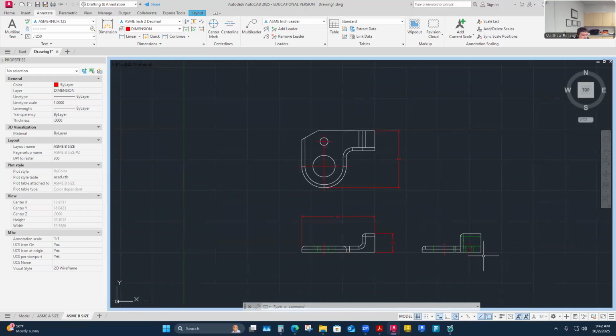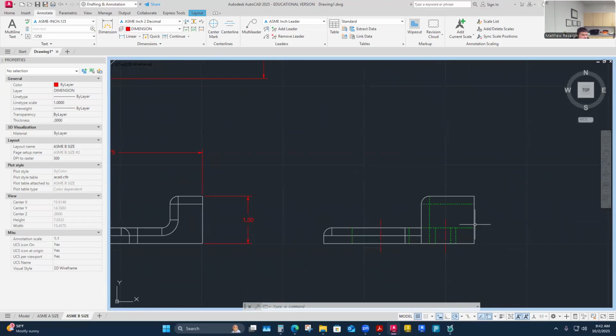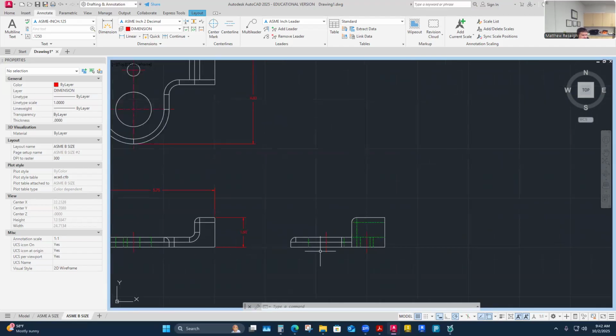And this one, I can look at it and know where the datums are. This would be one of the datums that I've established in the top view. This would be the datum that I've established in the front view, and then I really don't get this datum at all in this view. It'd be the surface right towards my face here. So I can't usually use it to pull many dimensions from in this view because it's 3D, it's going away from me.